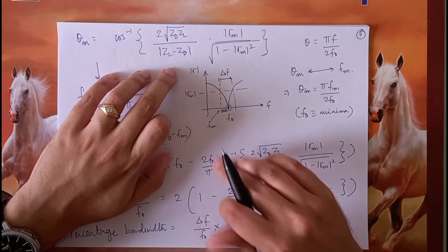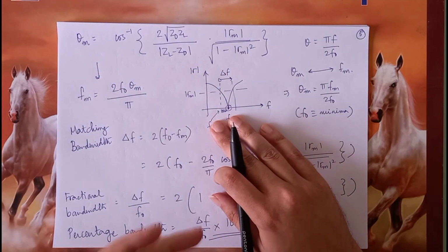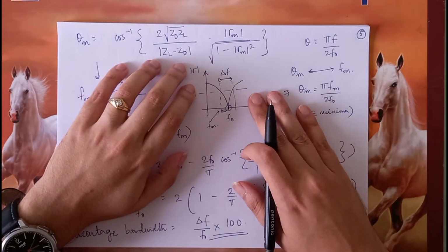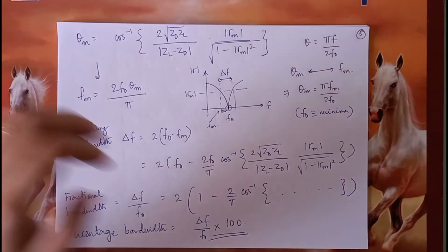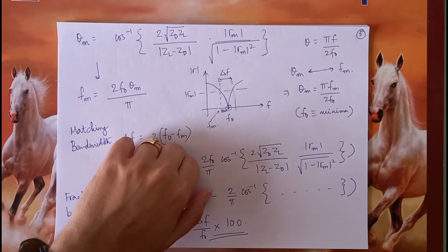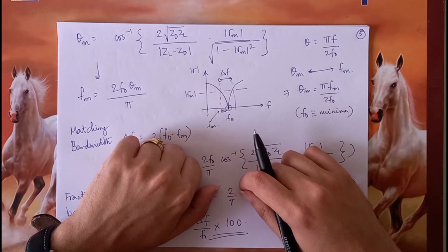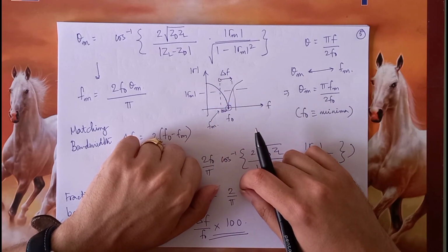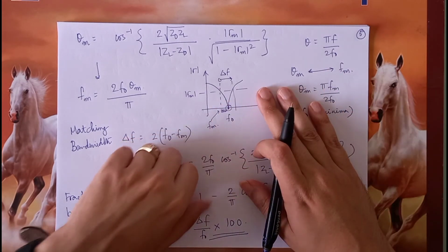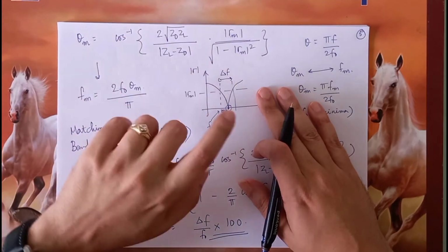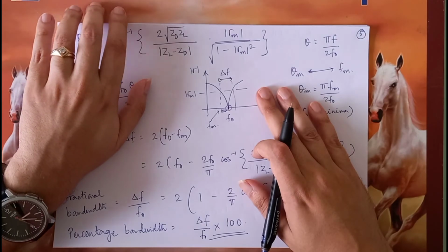But there are receivers and transmitters which often may need to transmit at different frequencies. So their operation is over a number of frequencies which may not be so close to each other. For those kinds of applications where the matching bandwidth required is rather large, the quarter wave transformer is not sufficient.